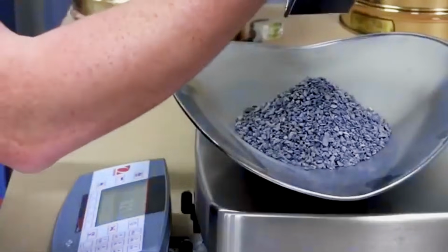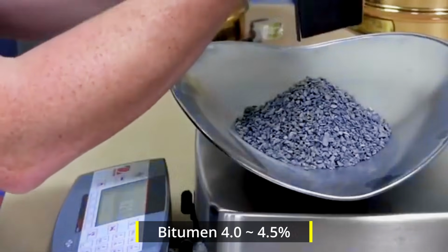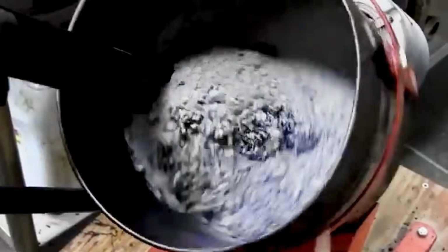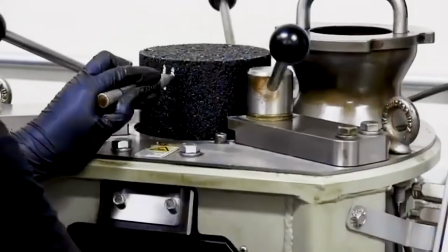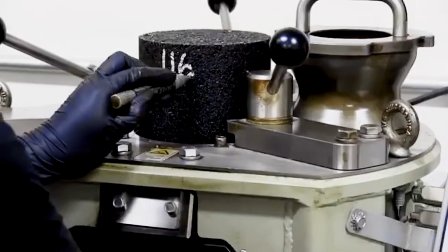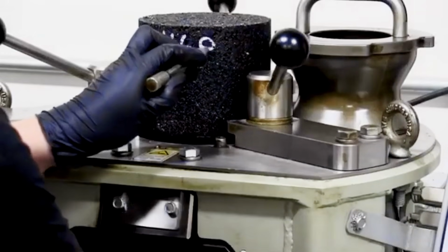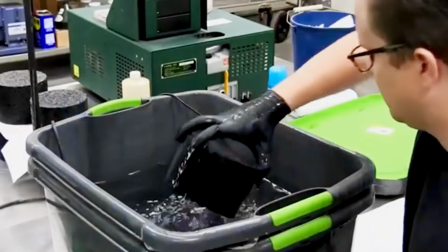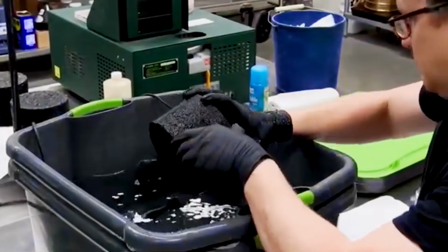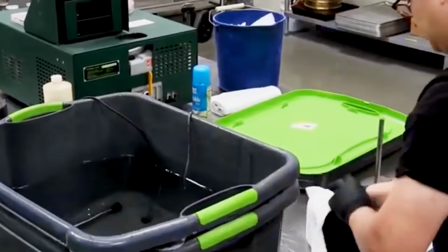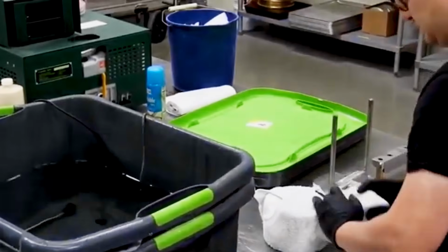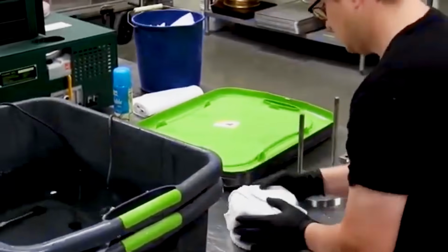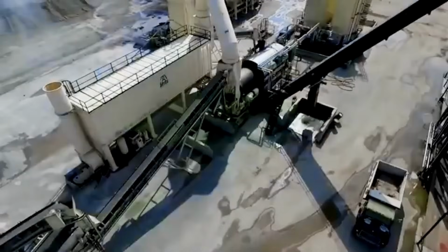Normally, the percentage of bitumen used for DBM is between 4.0 to 4.5%, in addition to meeting grading and quality requirements of individual ingredients. The mix shall satisfy all project specifications. The job mix formula shall be prepared and approved by the client before starting asphalt work. The formula shall be within specified limits and meet all quality control criteria. After approval, plant trials shall be conducted to confirm the bituminous mix design.